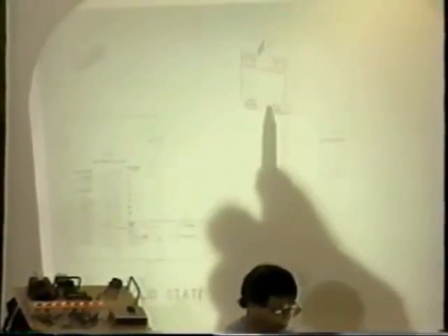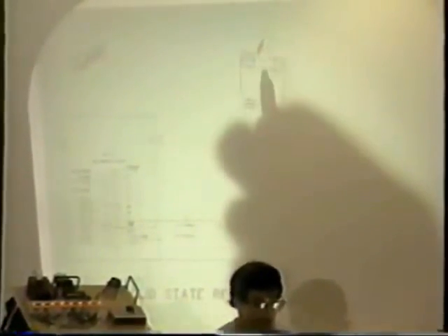Okay. There's a very special relay. And you know what's in this relay? A little tiny LED. Just like we were using here, there's a little LED in this. You know why? Because when you send out an LPRINT command, this LED goes on, and it sends a little light beam to a little transistor that's sensitive to light, and you're talking on a light beam between the low power end and the high power end.